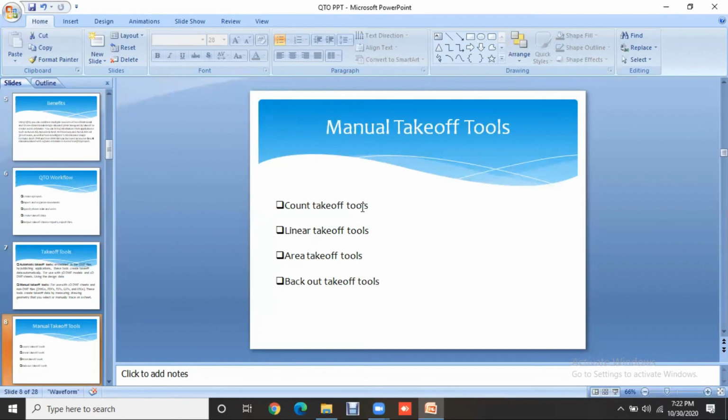So if you want to calculate the number of bricks and the materials on that wall, which consists of doors and windows, or any ventilations available on the walls, what do we have to do? First you have to reduce the doors, the window and the ventilation. After that you calculate the material.